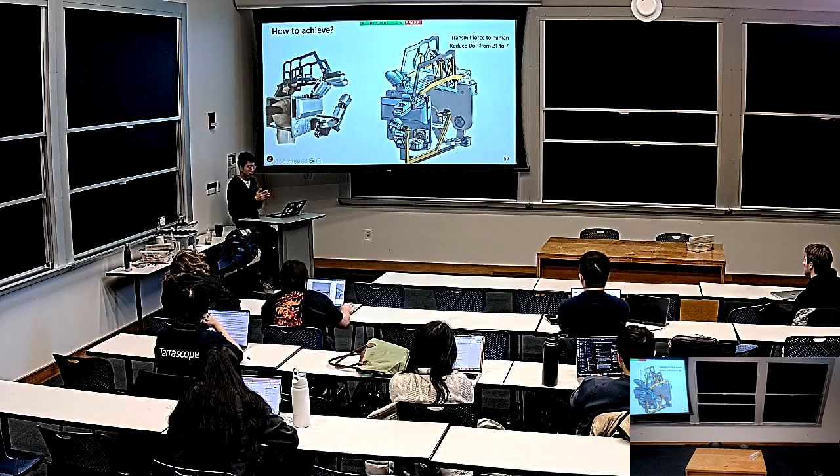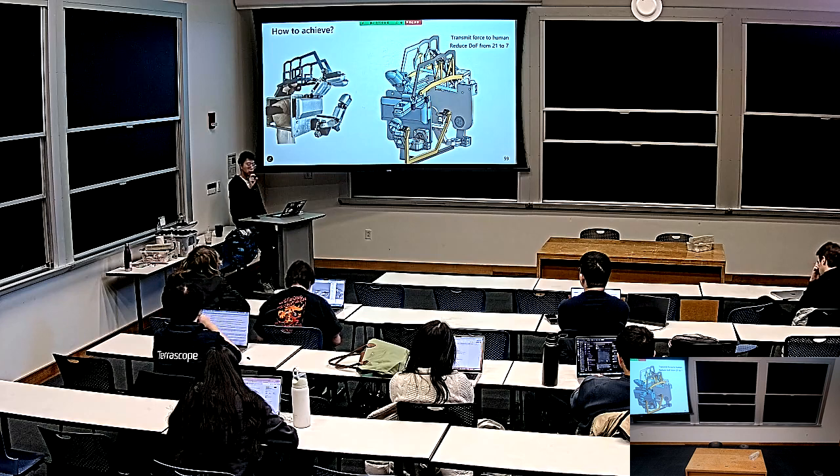When you connect them, it has two advantages. The first advantage is that the linkage can transmit the force from the robot to the human. So when the robot hand is interacting with the environment, when it collides with the table, the force will be directly transmitted to the human's hand. So now you will have haptic feedback when you are trying to do teleoperation, or daily manipulation.